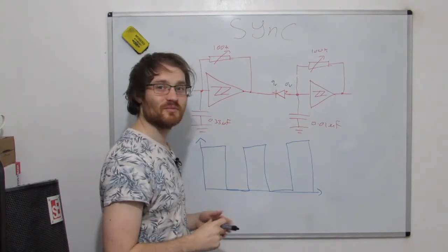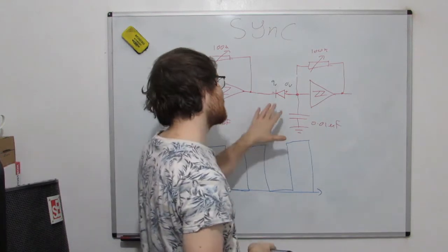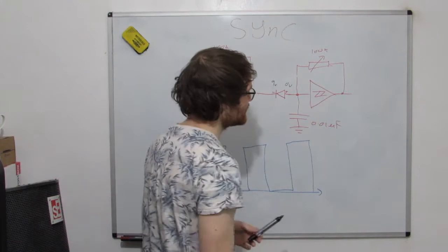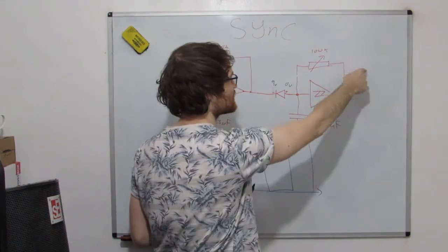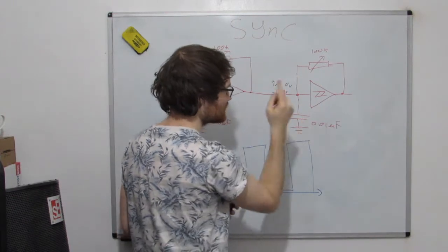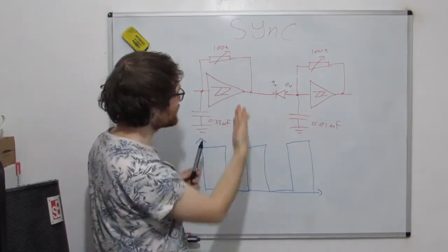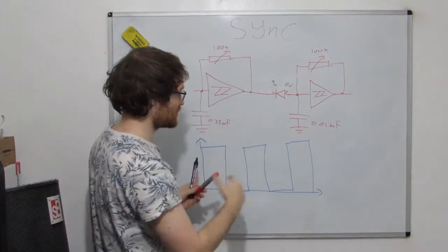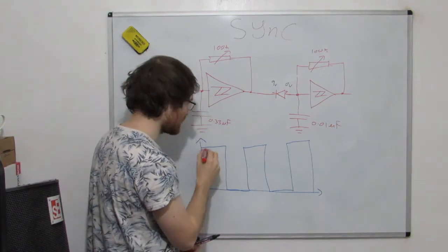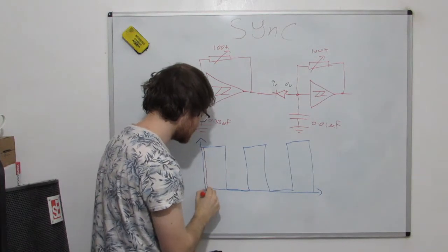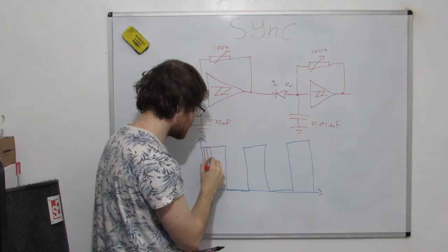So what's going to happen? Nothing, right? Well, no, not nothing, because we know what's going on here. This started off, and again this is inverting, so this is going to turn on. It's going to come over here. This is an open circuit, so it's going to charge this capacitor up, just like we did over here, and we're going to get a charge-discharge cycle. It's going to be faster than this one was, so this one's going to charge and discharge inside here.